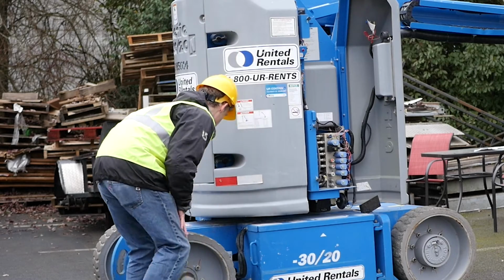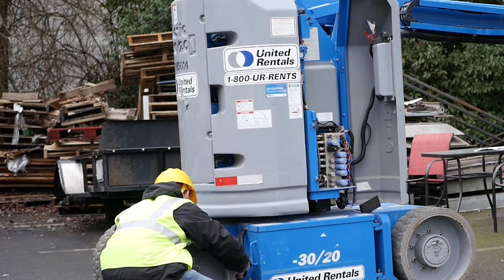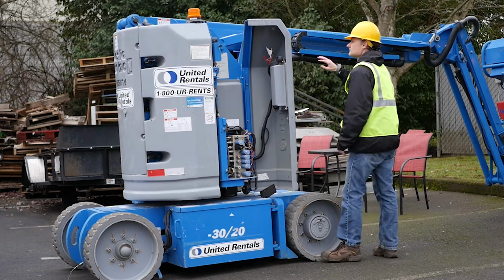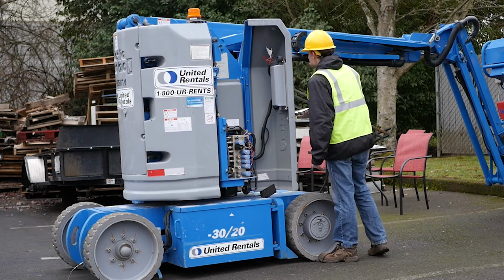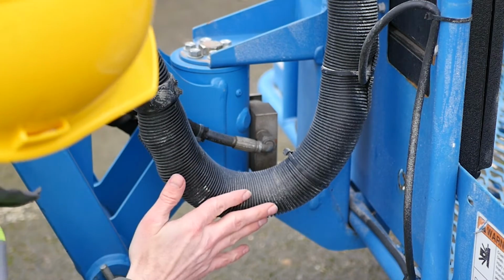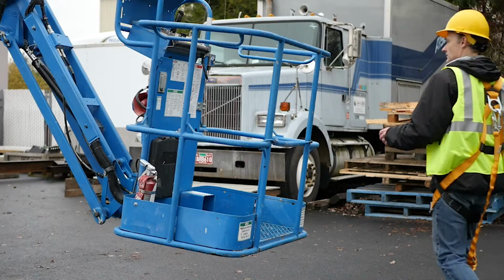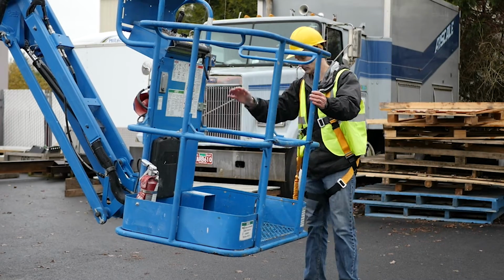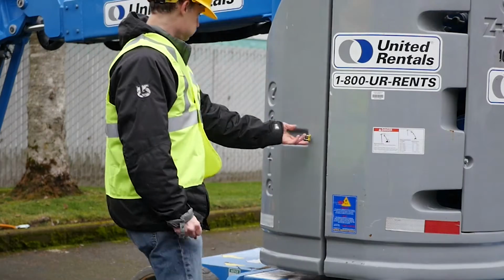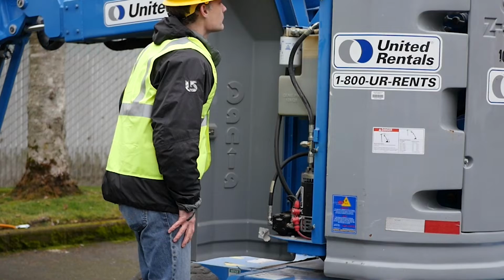An aerial device must be inspected by a trained operator each day before the lift is used. Conduct a walk-around visual inspection to look for damaged components, cracks or corrosion, excessive wear, and any loose, deformed or missing bolts, pins, fasteners, locking devices or covers. Inspect the work platform, including the guardrail systems, floor, anchorage, and mounting. Check for basic cleanliness and any signs of damage.